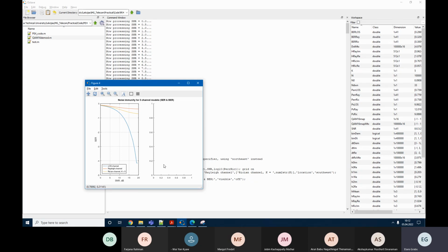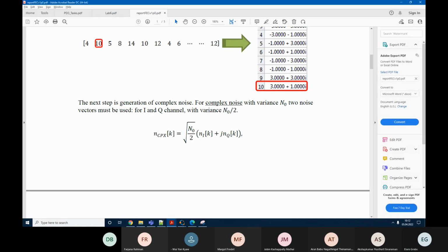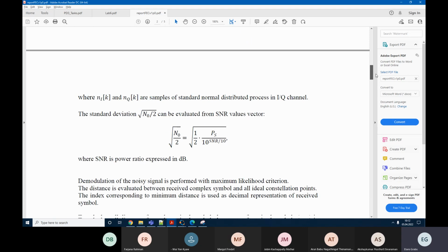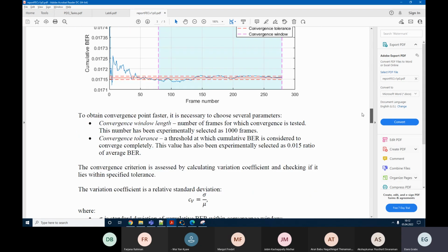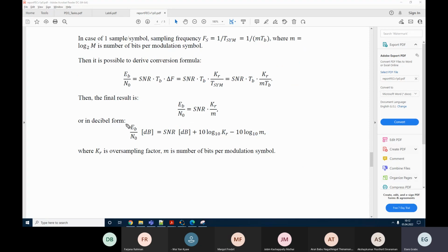So similarly, we'll now do for the bit error rate probability. However, for bit error probability, it's often convenient, instead of signal to noise ratio, to use some other variant called energy per bit divided by noise density, which can be recalculated from signal to noise ratio in accordance with this formula, right? So if we have this SNR in decibels, we can recalculate this energy per bit by simply considering that our symbol energy is 4 times greater than the energy of the bit, right? And N0 in its turn is actually signal or noise power.